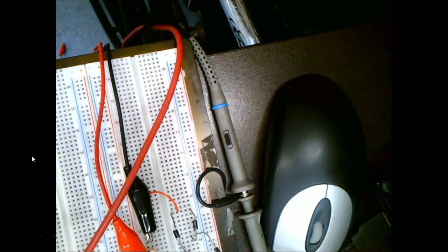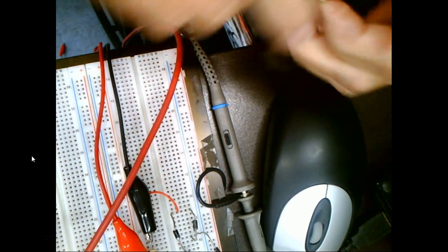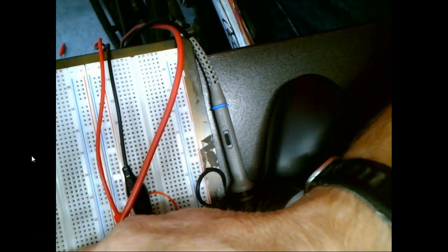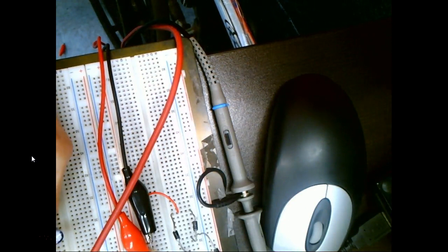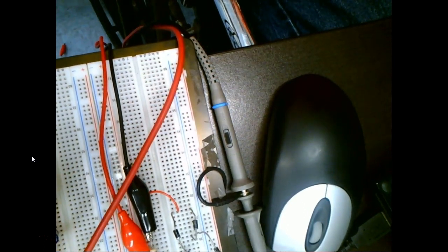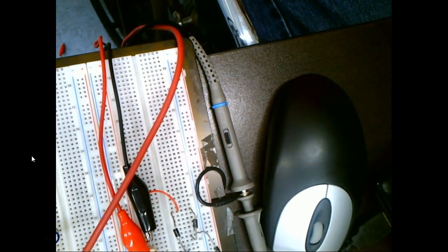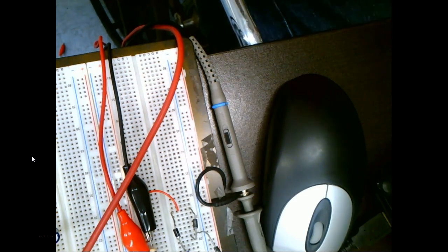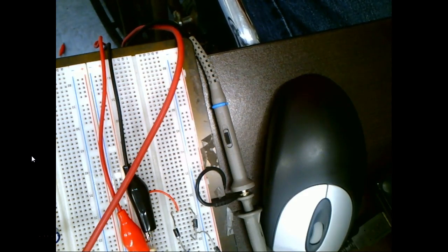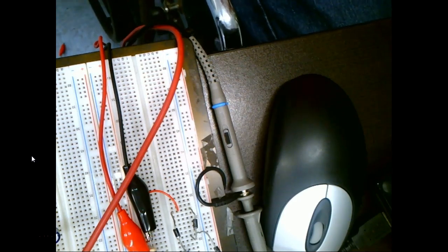470K. Okay. This is a brown, black, yellow, which is what I want. And then I'm going to put it in series with my capacitor. Now, what a capacitor does is when you've got one fully discharged, it basically acts like a short circuit. So as soon as you put a voltage across that thing, it would pull a ton of current to start off with. And then the higher it charges up, the less current it's going to pull. But the voltage across the capacitor would go up too, right?